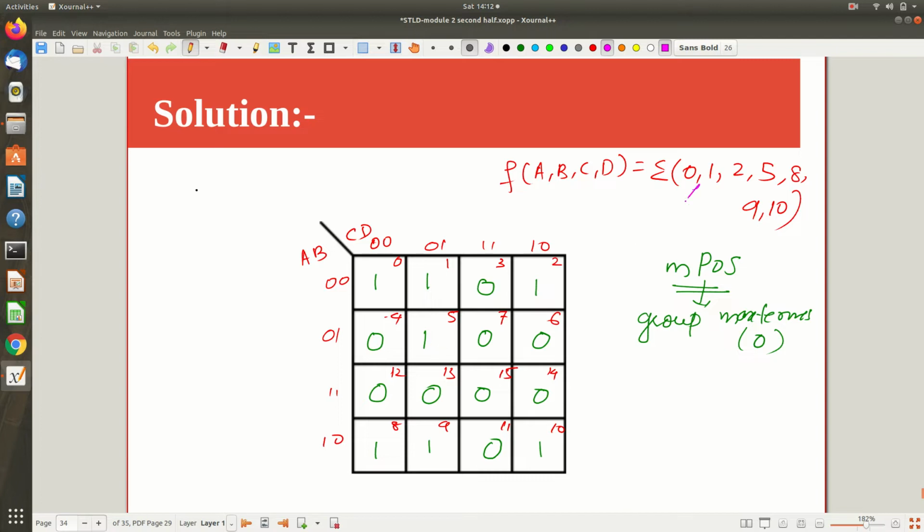This is the sum of product expression, the canonical SOP. Corresponding to each term, 0, 1, 2, 3 everywhere, I assume that these are all the product terms or the min terms. I put a 1 there. In the truth table, these are all the entries where I have a 1, and the remaining entries are zeros. And I need finally the minimum sum of product expression.